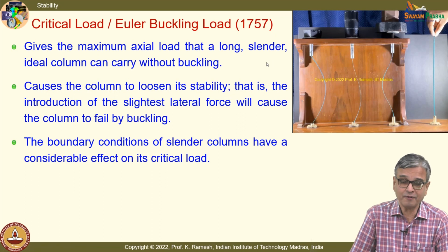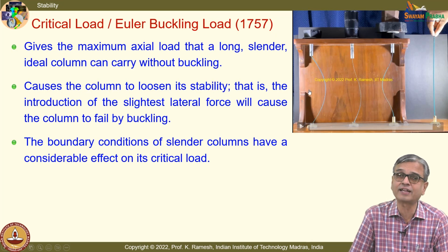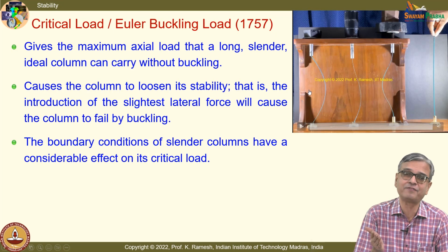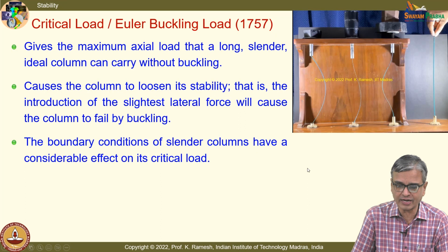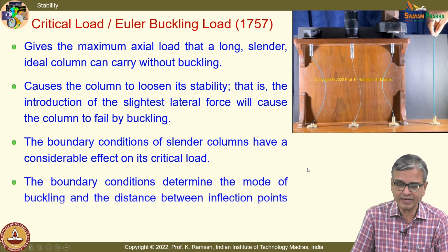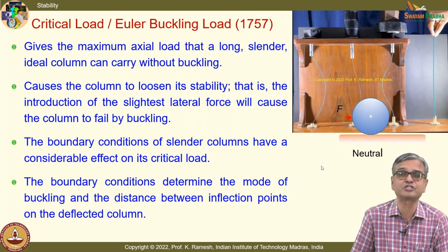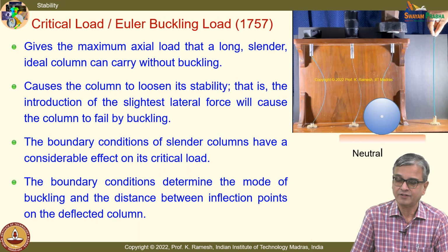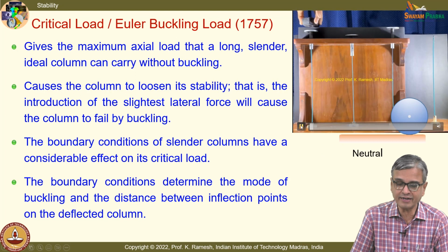Fine. And what we have also seen is, even if you go beyond the critical load, you will see a deflected pattern so beautifully in your experiment, though your analysis may be difficult. That is different. And I have also used this to show another aspect. We have discussed that these positions are neutral equilibrium positions. And when I redo this, you can recognize this has already buckled.